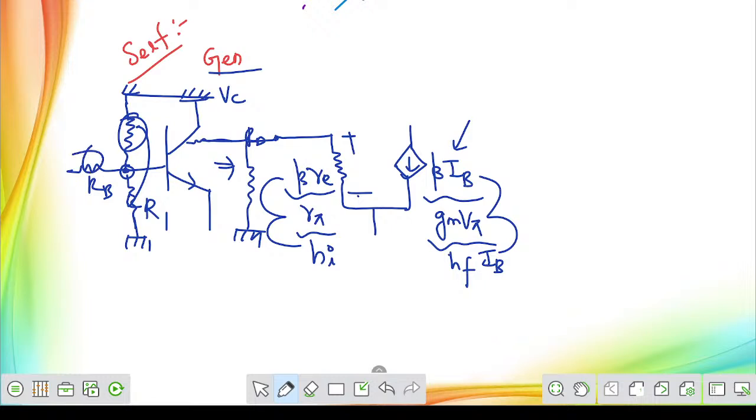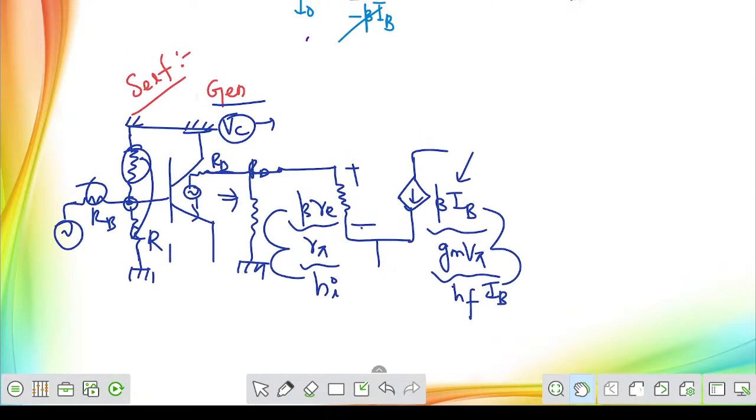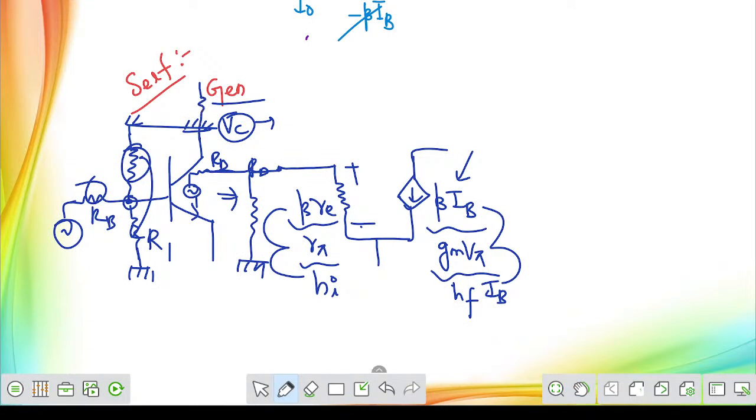After that, if a base resistor is given, yes, connect the base resistor. Then if a supply voltage is given, yes, connect the supply voltage. Then go to the collector terminal. Observe whether the collector is directly connected to the ground; then connect it directly. No sir, there is some resistor. If the collector resistor is given, see, across the collector terminal, if they are giving RC like this and they are measuring the output voltage, simply connect this with the ground.